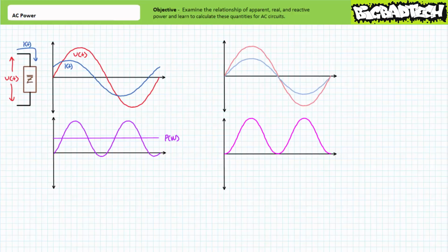In summary, there's some similarities and important differences between the plot of power where there is a phase shift between voltage and current, versus an imagined state where there is assumed to be no phase shift between voltage and current. Really, all we've done is shifted our original plot of power upwards such that all power is assumed to be positive or above the horizontal time axis.